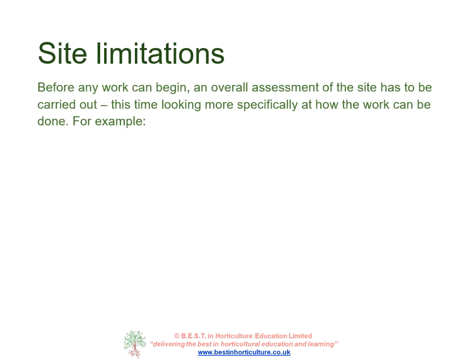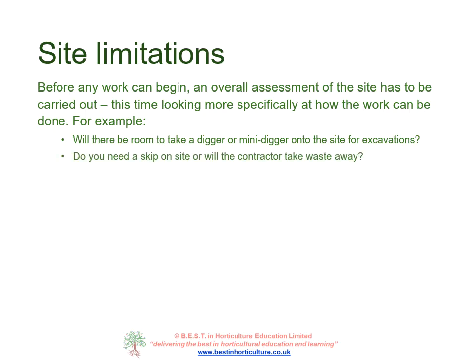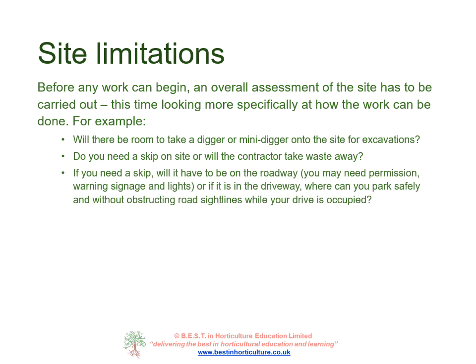Site limitations. Before any work can begin, an overall assessment of the site has to be carried out. This would be the common practice with any design work, and we've dealt with site analysis or site evaluation in previous topics. But this time we need to look more specifically at how the work can be done. For example, will there be room to take a digger or a mini digger onto the site for excavations? Will you need a skip on site, or will the contractor take waste away?